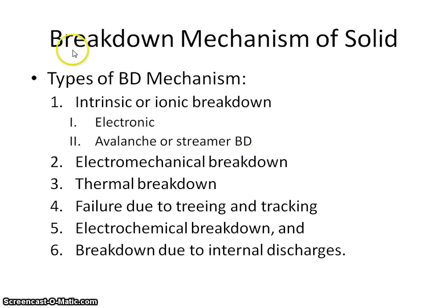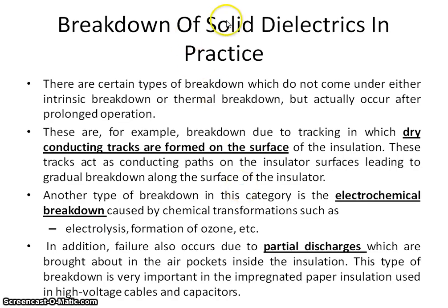In the continuation of breakdown mechanisms of solids, the types of mechanism we already discussed are intrinsic ionic breakdown, electronic breakdown, avalanche or streamer breakdown, electromechanical breakdown, and thermal breakdown. Now, in the continuation of the breakdown of solid dielectric, we know that there is a certain breakdown which does not come under either intrinsic breakdown or thermal breakdown.